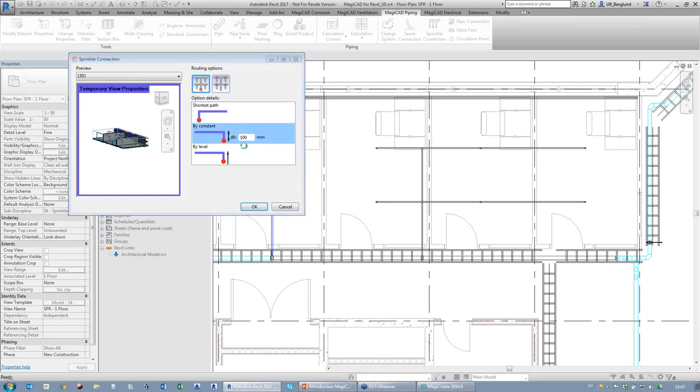And in the same way here, we can go and change these. Sometimes it will work, and sometimes we will get this pipe connection problem, for instance. In this case, it gets confused about how to do it in these 2 parts. It needs to go up and at the same time, we don't have that kind of part. So we can still make this and it will not connect, and then we can go in manually and fix those small features. But the important part is that we get a message that tells us if something goes wrong.